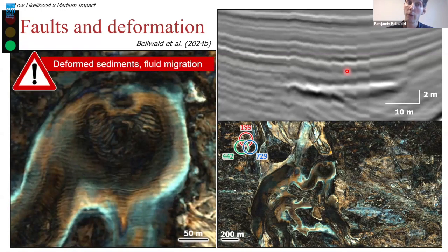But deformed sediments, obviously, if you have faults and deformation, you may have some deformation problems. And it could also be that these faults are acting as fluid migration pathways. So be cautious, especially if you work in the Baltic, for instance, where you may have a lot of shallow gas. Good, but it can be observed in tunnel valleys.